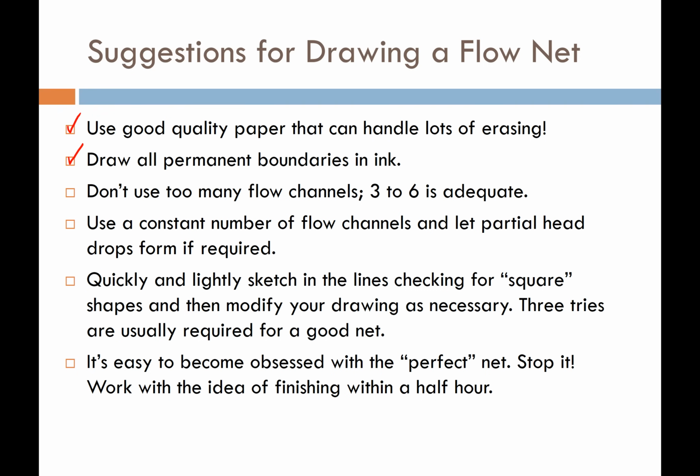And that way, if you erase flow lines or equipotential lines, you don't have to keep redrawing those boundaries. I recommend that you don't use too many flow channels. I have found that 3 to 6 flow channels is adequate. If you're putting more than 6 flow channels on a problem, you're going to be doing a lot of drawing and erasing. 3 or 4 is great. 5 and 6 starts to get a little iffy. I wouldn't ever do more than 6.